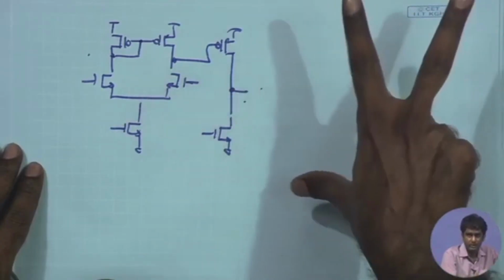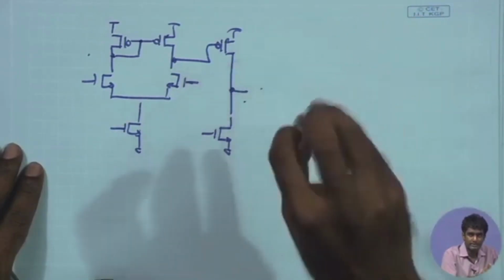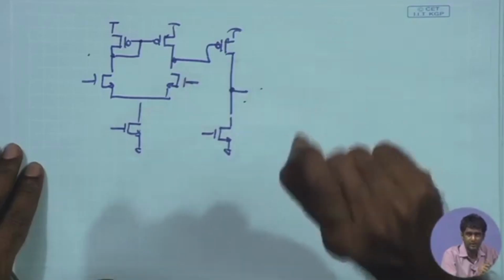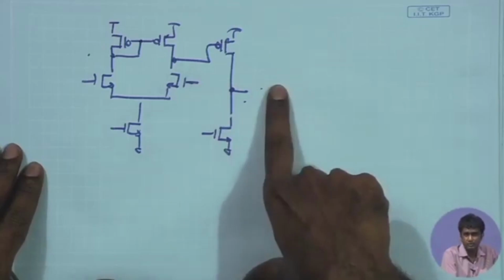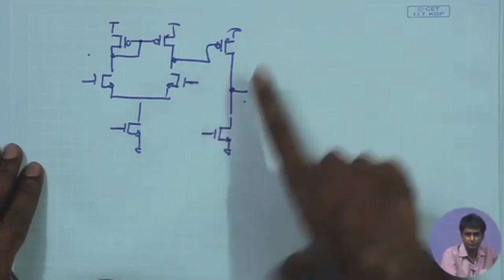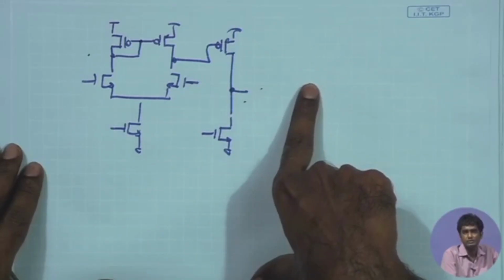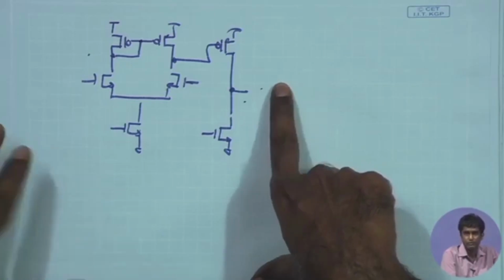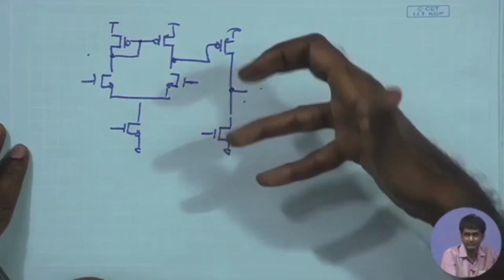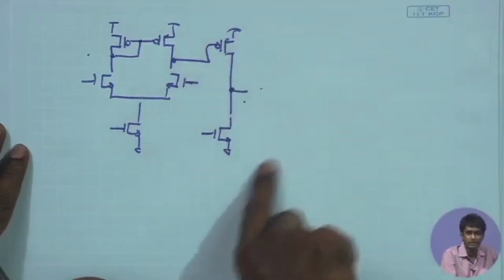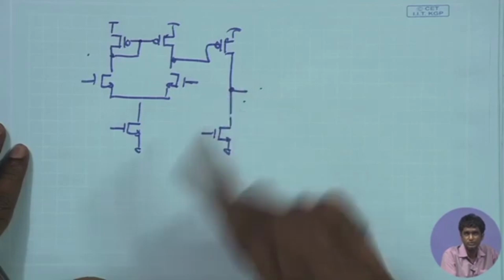In the differential half, you have the common mode extractor, which is automatically extracting only the common mode DC value or slowly varying common mode value. But here if I try to extract the DC value just for establishing a bias point, it will require very large R and C values or filter values to implement such a common mode feedback, or rather a DC feedback, to stabilize this to the required value.